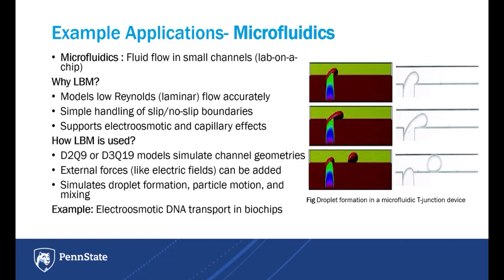Next, we have microfluidics, the study of fluid flow in micrometer-scale devices. LBM is ideal for this domain because it handles low Reynolds number flow very well. It also supports both slip and no-slip boundary conditions and can incorporate electrokinetic forces, which are common in lab-on-a-chip systems.